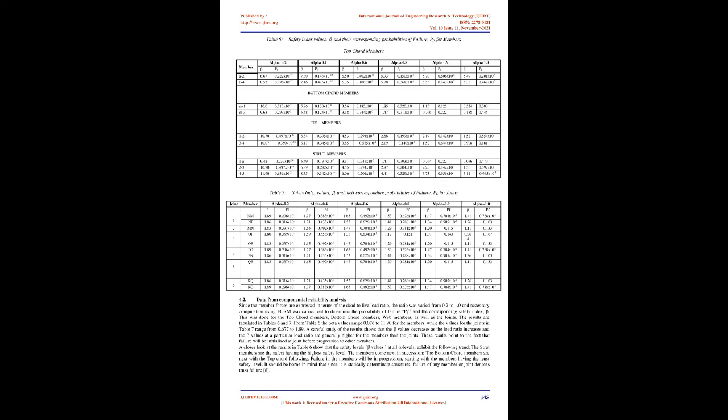5.0 Conclusion and Recommendations. The reliability-based design of Eurocode 3 procedures for a Mansard roof truss system has been carried out with the aid of computer programs in the Fortran language. The FORM analysis for the elements was carried out using FORM. From the results obtained for the first-order reliability method, the safety indices range between 0.076 and 11.90 for the members,